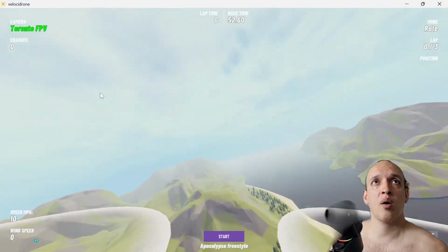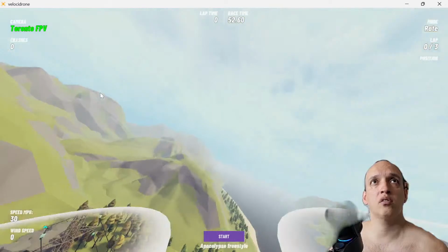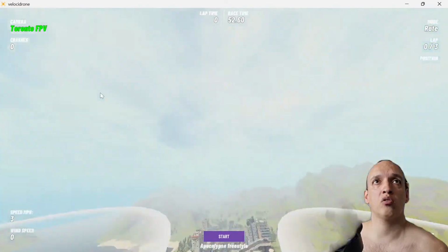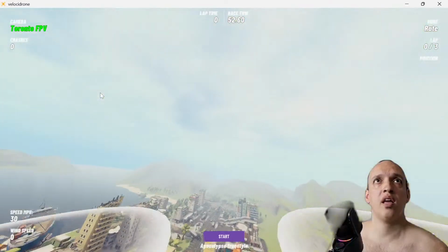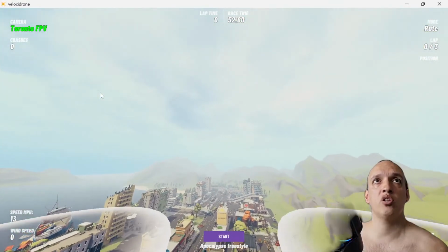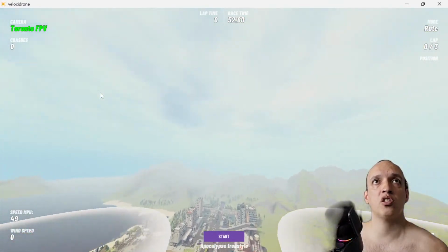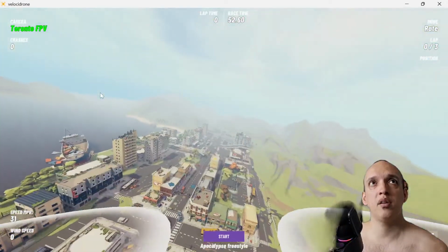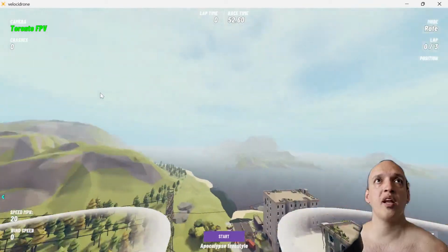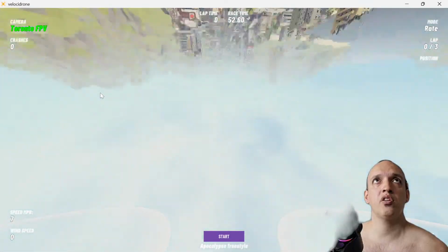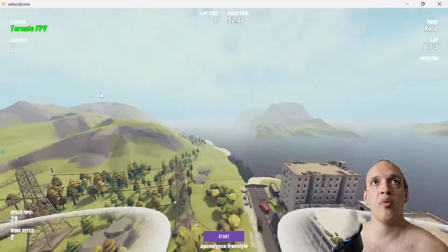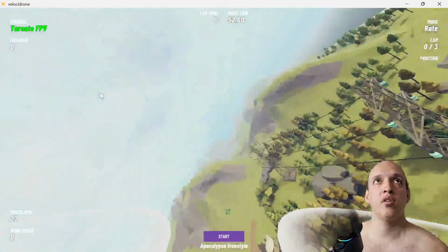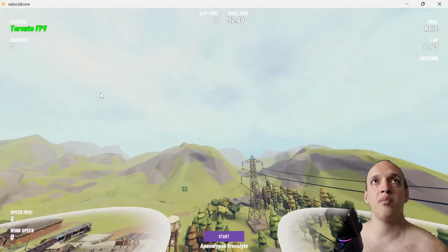So you can go drop the throttle, go to the right, go to the right. Now drop the cut, go up, drop the throttle, go to the left, and then go to the left. And you can do this slow and smooth, or you can try and do it faster. So watch this. Snap it, snap it. Like you can start off by going kind of slow, go up till you see that, and then you can go backwards, and you're back straight up. You can go to the right till you're upside down. Now go to the left, and you use the horizon to keep yourself balanced.